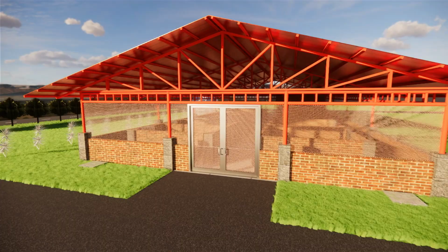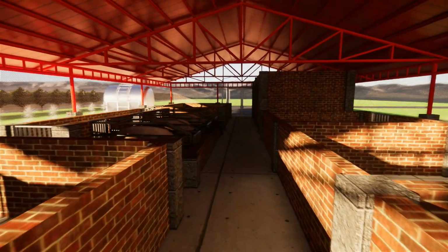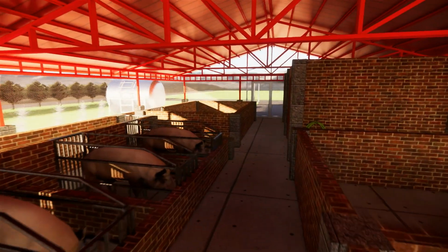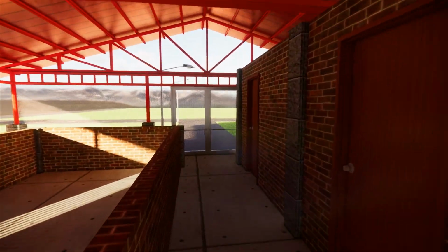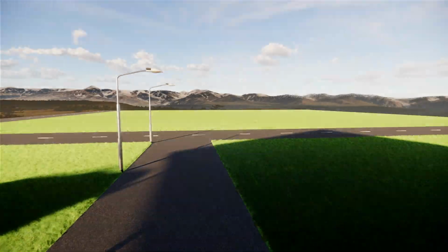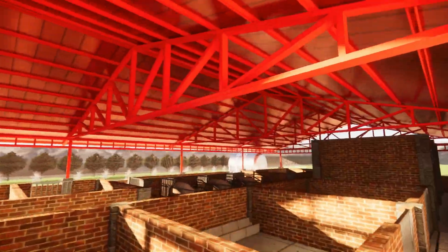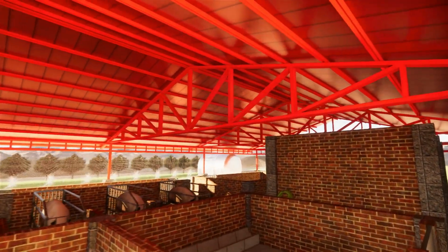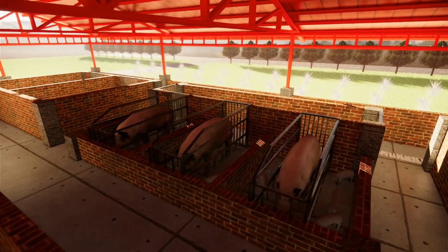This 3-unit system design adheres to the standards, including space requirements, feeding, and watering facilities, ensuring that the swine housing is suitable for the local conditions and meets the welfare needs of the pigs. The design process takes into consideration various factors such as the ceiling height, which is recommended to be 2 m or higher, and the building sidewalls, which have a minimum height of 1 m. These standards are important in ensuring the health and productivity of the swine population in the Philippines.